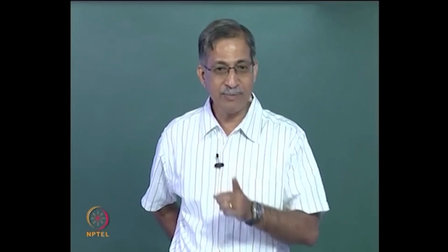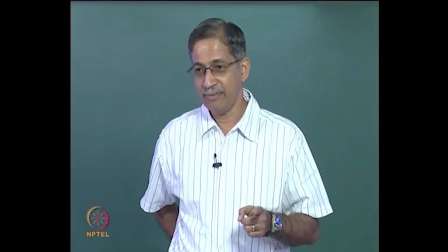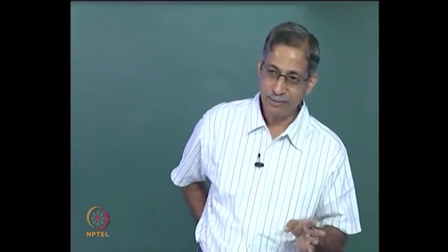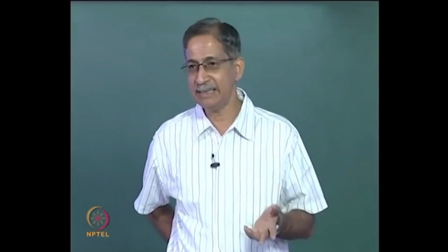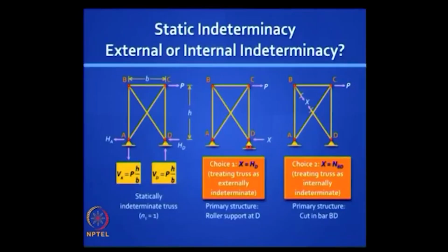So the stiffness of that member BD has a role in governing the answer of X. So do not remove members, you just cut them. When you cut them, you release the member, right? So we will examine this more carefully later. So you have multiple choices of indeterminacy here, and it is left to you whether to treat this problem as either externally or internally indeterminate.